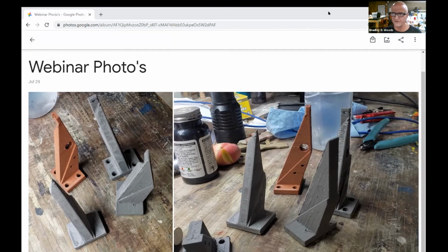And I think you did that, right, Dave, for that Autodesk part? I did, yeah. I don't know if on this slide or the next one we're going to talk about internal channels, but the thing that I found is that you can do that. If all the requirement is that the cooling channel stays intact, for example, the design was a circle, but after sintering, it collapsed a little bit and became more oval shaped, that's okay, as long as you're still getting the cooling that they're looking for in the part.